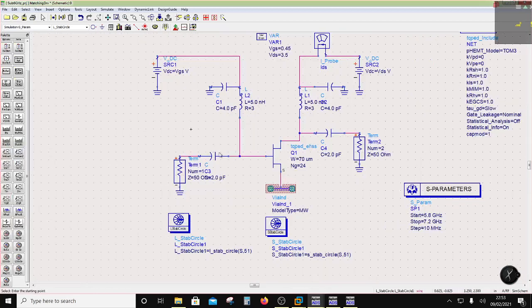Okay, so for a device, gamma in is looking into the input and gamma out is looking into the output. Now if I put energy into the input and the same energy reflects back, exactly the same amount, then gamma is 1. Similarly, in the output, if I put some energy and the same energy goes out, gamma is 1. And gamma equal to 1 is a borderline.